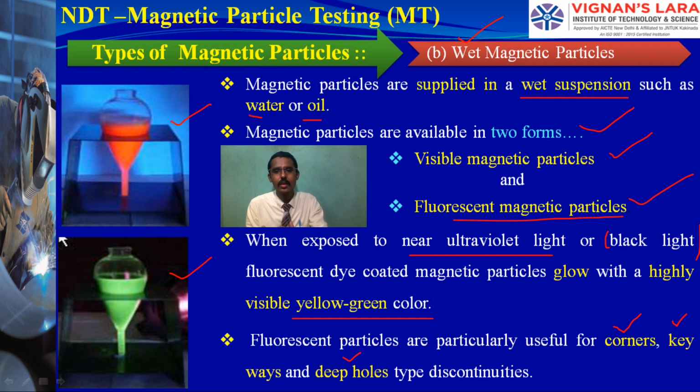So it is not normal through the visual eye. We come to other types of NDT inspections only when the cracks are not visible by normal vision. Then only we use magnifiers, contrast colors, and some liquid penetrant poured over to generate contrast.